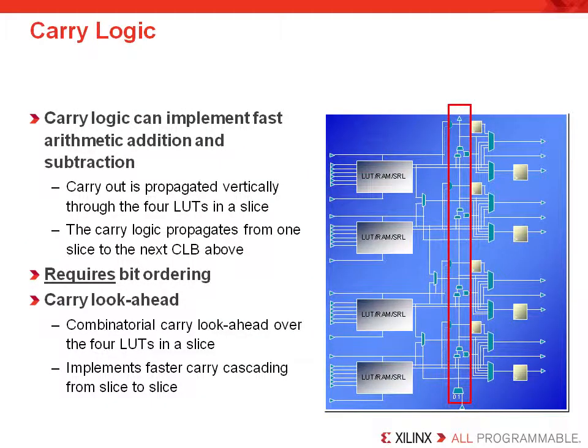Carry logic is a dedicated hardware resource that improves the speed of arithmetic functions, such as adders, accumulators, subtractors, and comparators. From the diagram, you can see that the slices are grouped into one carry chain. Please note that carry logic will propagate the carry signal vertically upward.